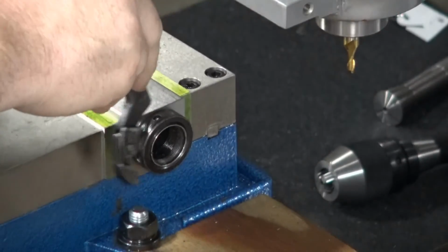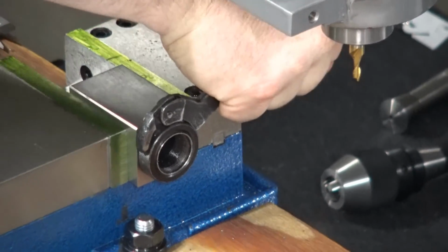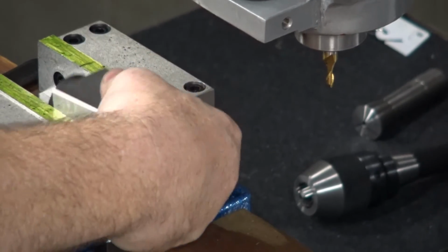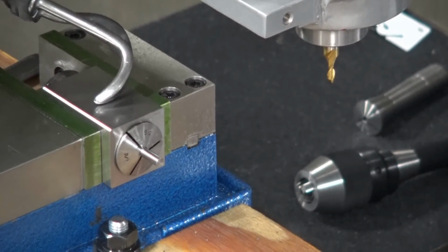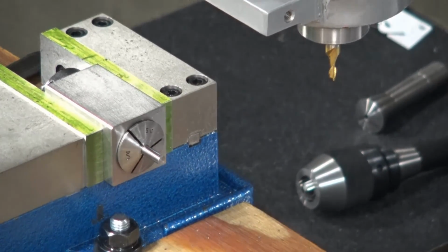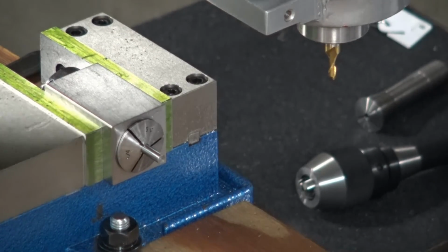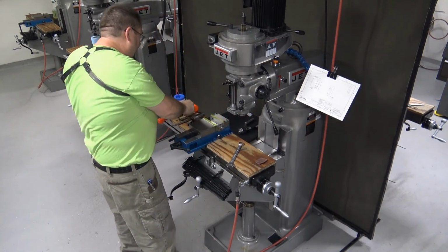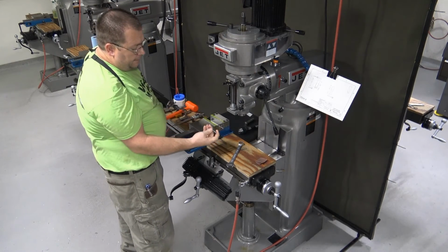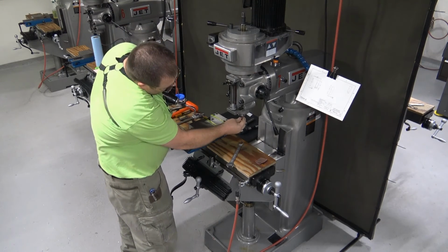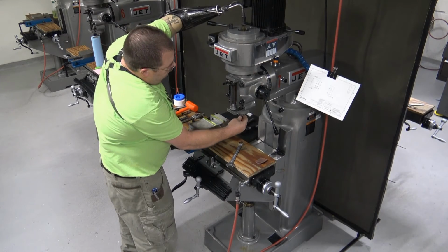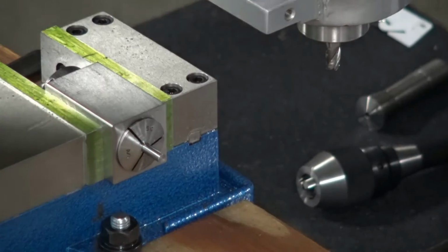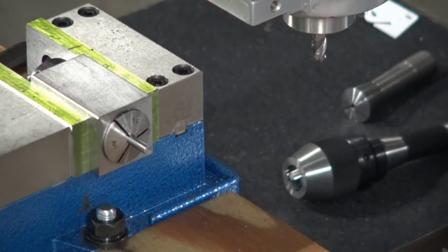If you recall, we said that we needed to pick a size end mill that would cut the full width of that flat all at one shot so that we're not moving side to side. I believe I told you that my preference is to use a 3/8 end mill. So we're going to take that 3/16 end mill out. I'm going to leave that same R8 collet in there, because my 3/8 end mill has a 3/8 shank on it. So I'm going to feed that up into my collet. I want to have enough stick out that I don't run into the collet block.